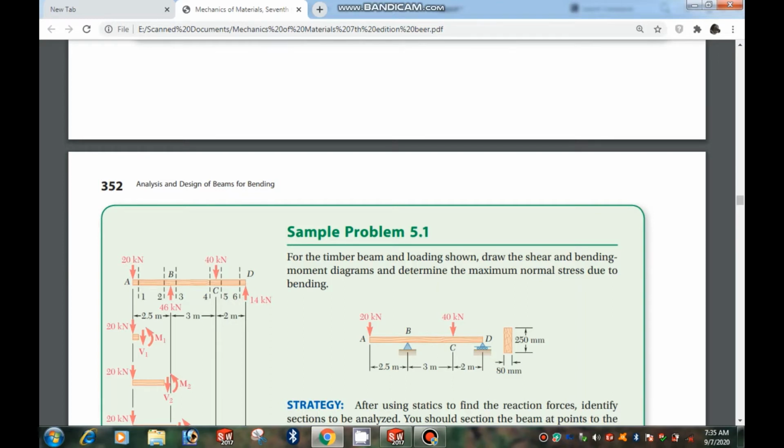Make sure that during the extrusion lengths of 2.5 meter, 3 meter and 2 meter, we have to uncheck the merge result. This we have to do because during simulation we need joints for the application of external load.